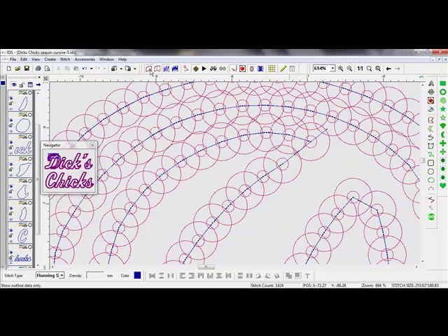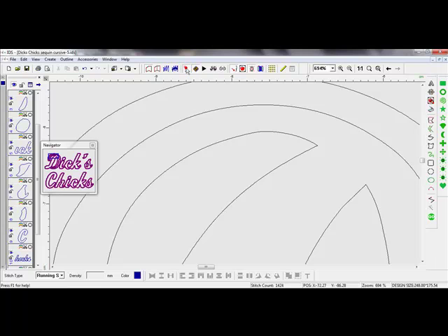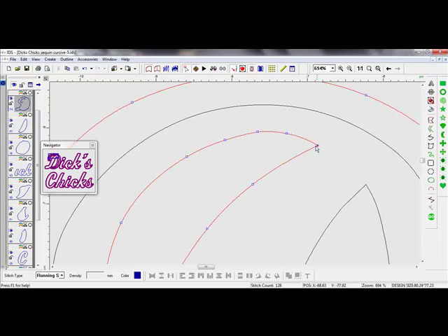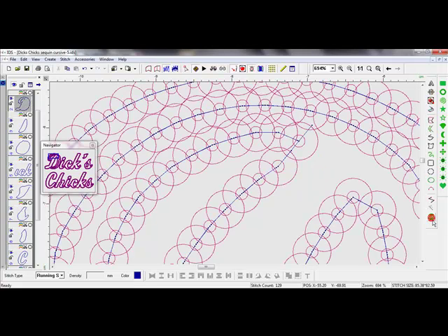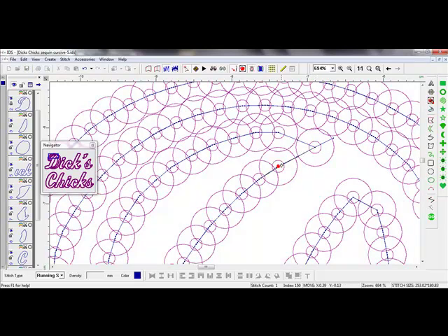So we can do a couple of things. We can go into the outline view in the edit outline mode, and we can take this and we can move it, and let's see if that changes the way the sequence lies down. It changes it a little bit, but not quite what we want. The other thing we can do is that we can go to the edit mode within the stitch view, grab the sequin, left click on it, and then left click, hold, and drag. When we left click, hold, and drag, you can see that sequin reposition. Maybe we take this one as well.